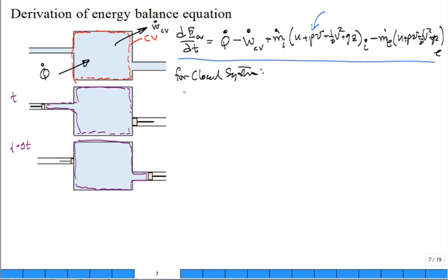We're going to say that the energy in the control mass at time t is going to equal the amount of heat that came in over a time interval by heat transfer minus what went out, think shaft work, across the boundary during a time interval.